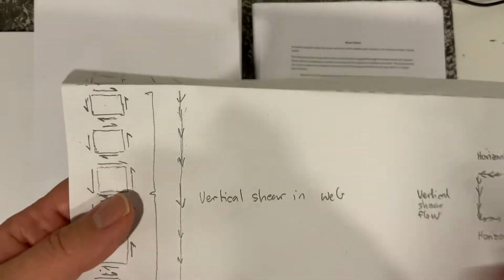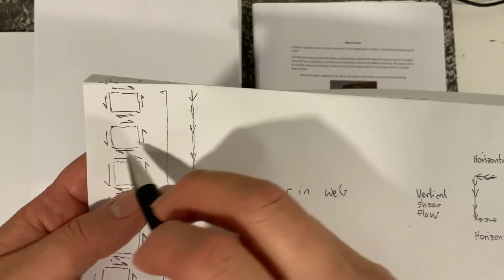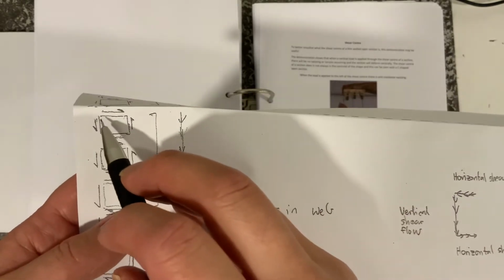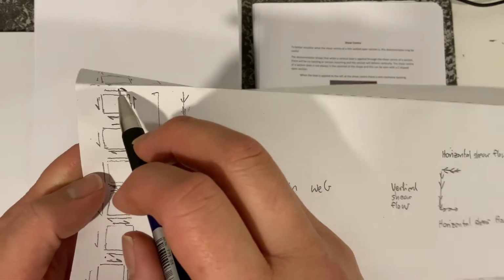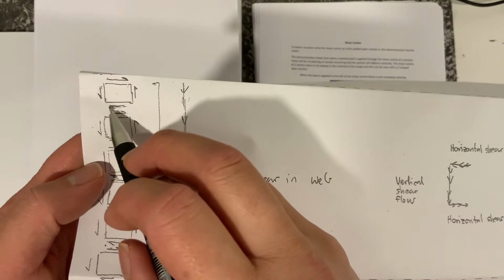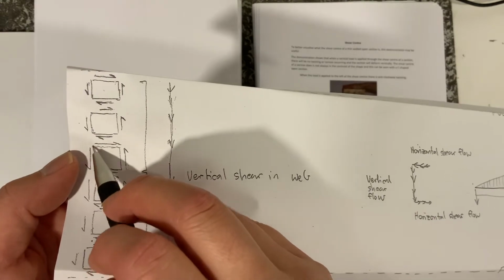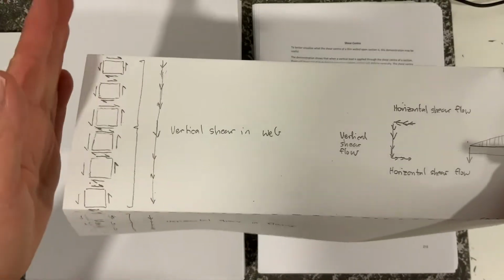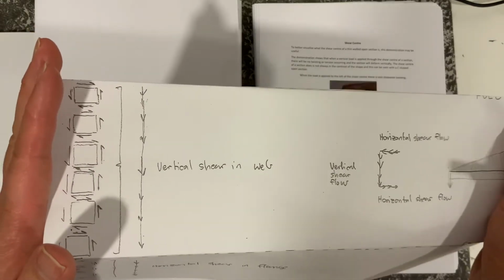And we can see the complementary shear stresses that we talked about last time, so these would be the vertical. On the other side, of course, it's going upwards for equilibrium. But what I'm drawing attention to are these ones here. These would be the horizontal shear stresses, which would be in equilibrium with the vertical ones. If that helps you understand what it means when you put the load going downwards or upwards, it doesn't really matter which direction.